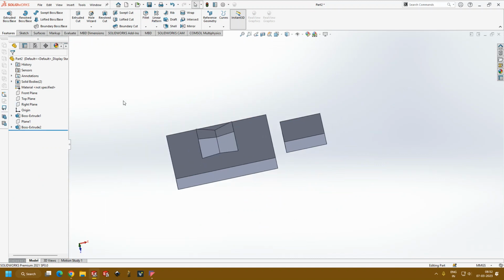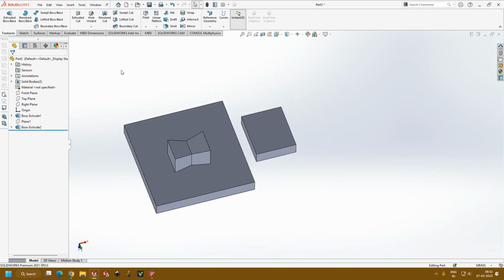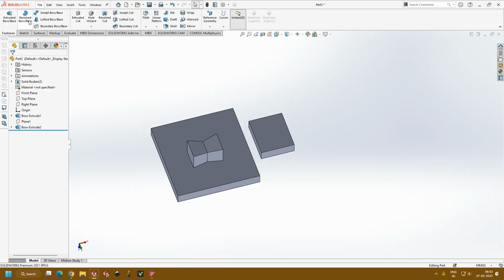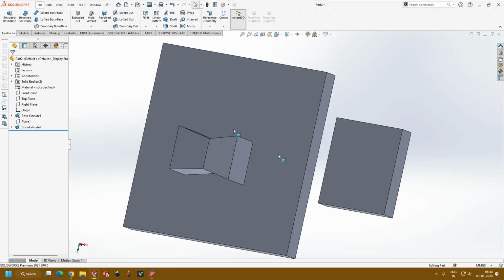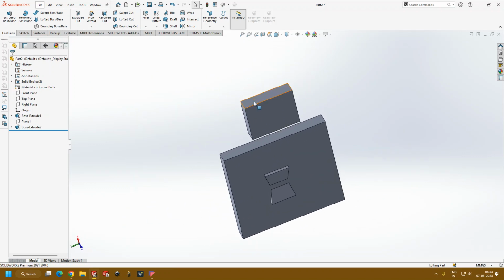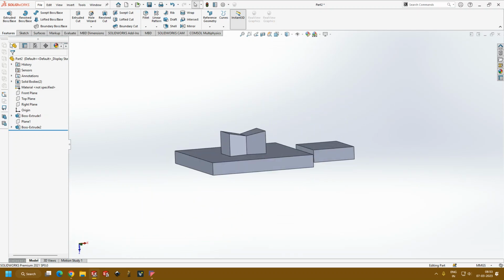And now today we can see another option called revolve. Or one thing we do, since we have seen extruded boss, we'll see the extruded cut option directly. Then after this, we'll go to revolve. Okay. So extruded cut is, let's say, when you will be designing an encapsulating box using a 3D printer, you require some slots for your electrical connections or openings. So let's say, in a simple way, I'll just create a box first.